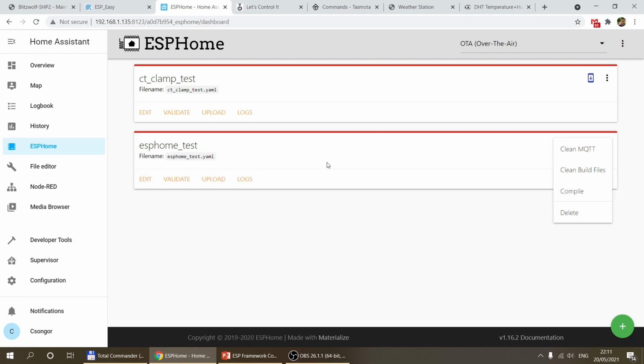So if you are only using 2 sensors, the code is going to be much less because it's not going to include the code for all the other sensors that Tasmota and ESPEasy include. At the end, it doesn't really make any difference for you. That just makes it easier to deploy and over-the-air update ESPHome on smaller devices, because let's say if you're using a Sonoff Basic, it doesn't actually have any sensors. It just has some button inputs and then a relay output. So the ESPHome firmware for that Sonoff Basic is going to be much smaller than the ESPEasy and Tasmota one,